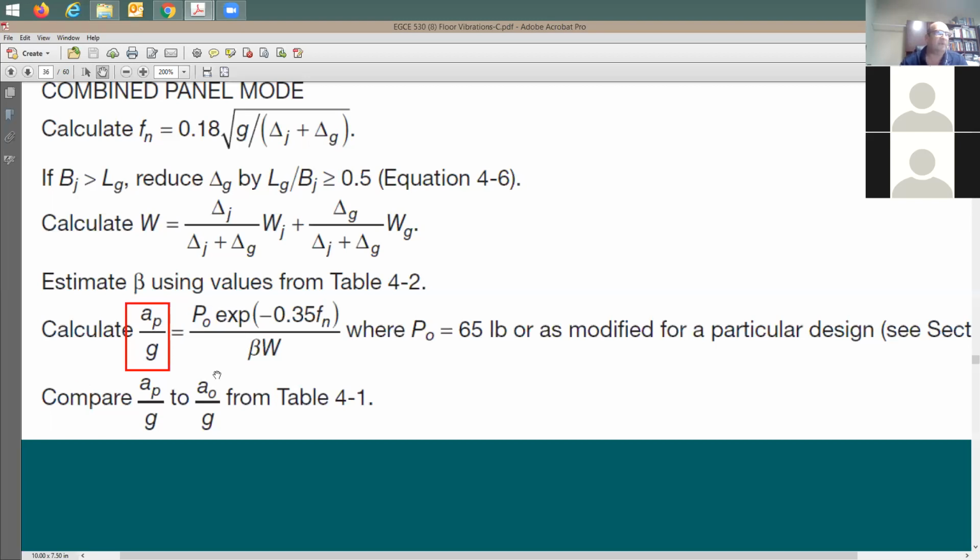So you need to be careful. You need to play with this damping. You need to play with the stiffness of the beam. When you go to a stronger beam, now the vibration effect is going to be much less. And then you can combine them and compare it to the 0.5% if you can.